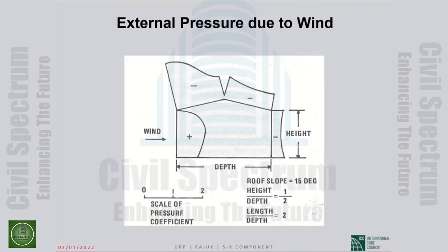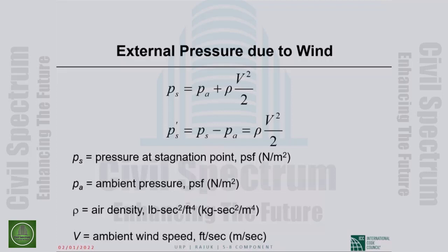Now, in concrete construction, none of this can happen, obviously. You don't have a wood structure anchored to a foundation. But still, there are non-building structures, there are tanks, there are things that are attached by anchor bolts, and you have to be aware of this huge suction that wind imposes.